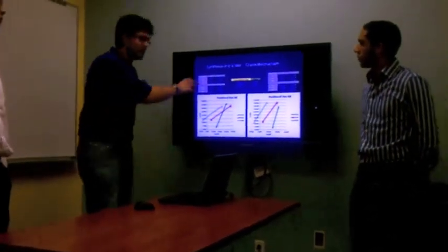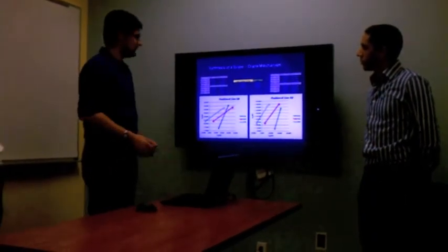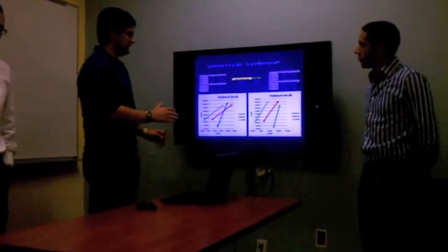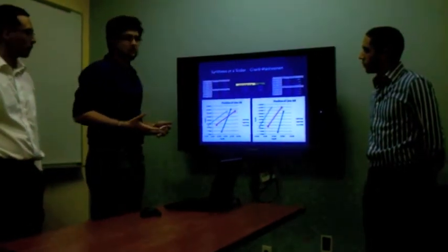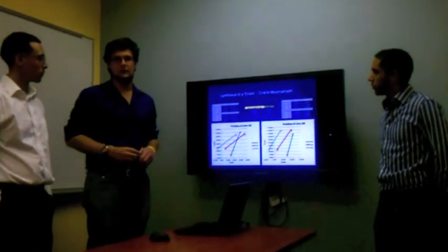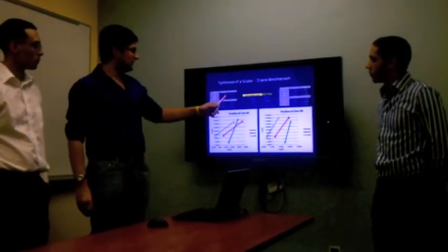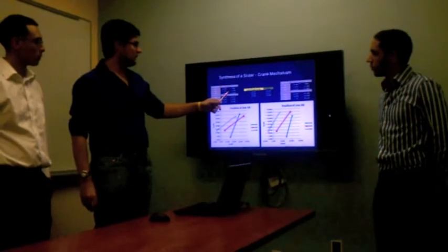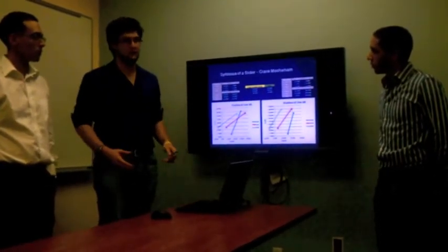Now, these were our initial values. When using our initial values, when we tried calculating the pole position 2, 3, there were no values. We were dividing by a determinant of 0, and that was mainly because values for A2Y and A3Y were the same, and values for B2Y and B3Y were the same.